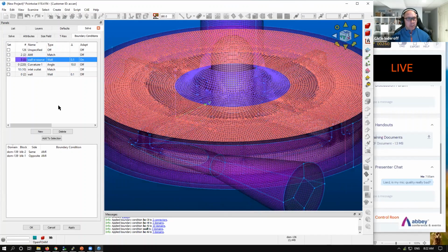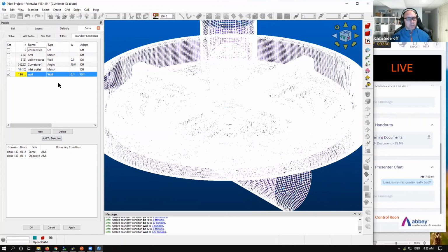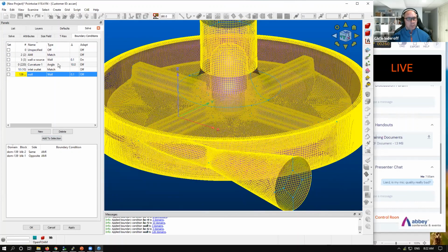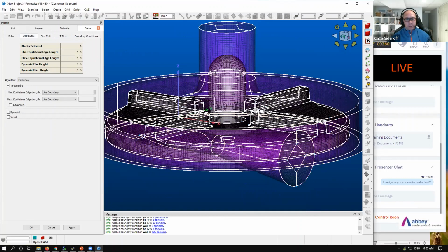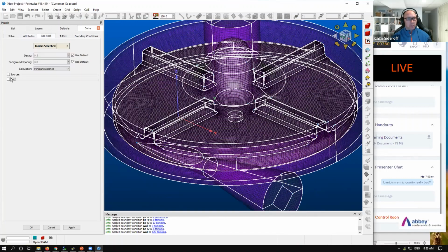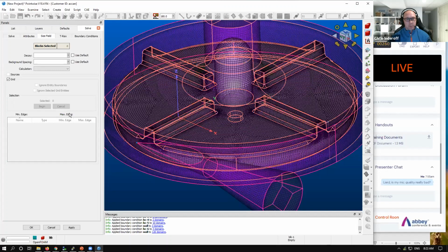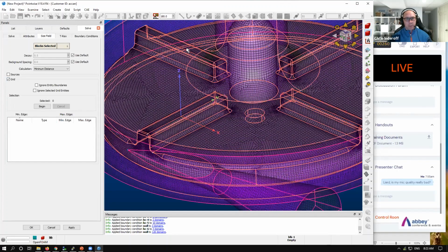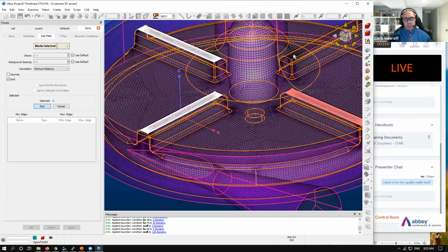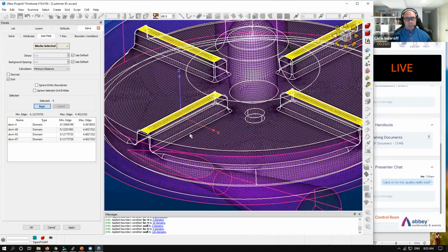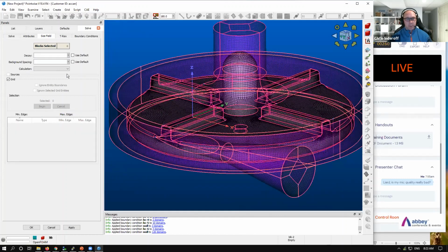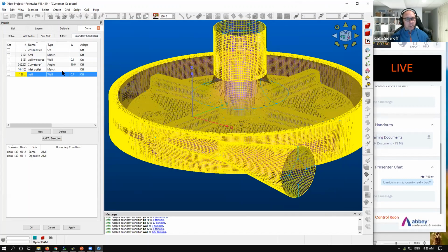Right? So everything else now, I'm going to put in this wall boundary condition. So I'm going to go over here. I'm going to create a grid source. This is where the adaptation is going to work. So use the top of the rotor blades as a source to influence the housing. What happens when the volume mesh runs is it's going to adapt the top. Ideally, you could say, well, why don't we just set everything to be grid source to itself? That can really slow down the calculation time. So I think I got all that.